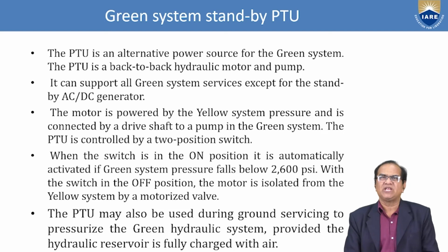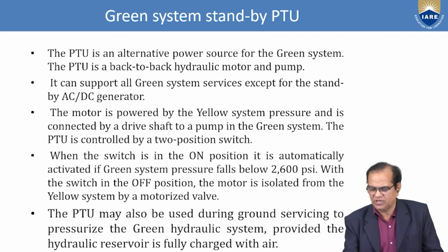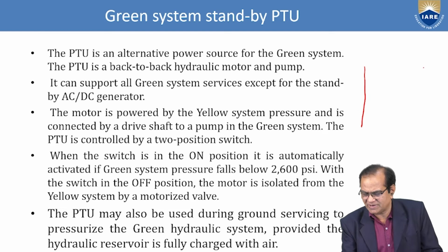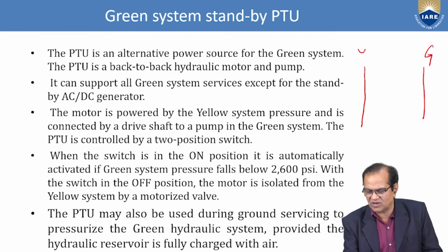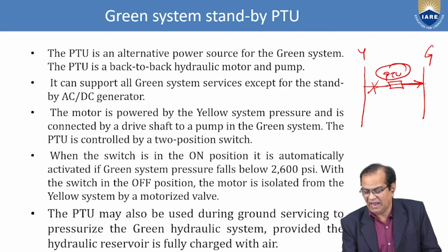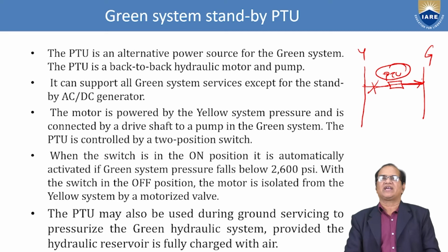The power transfer unit, okay, what is this power transfer unit? This is the yellow system and this is the green. Just I am writing green and the yellow. This is called the PTU. If this system fails, then this starts supplying from here to here. This is the system which will connect green to yellow and yellow to green. That is the purpose of the power transfer unit.